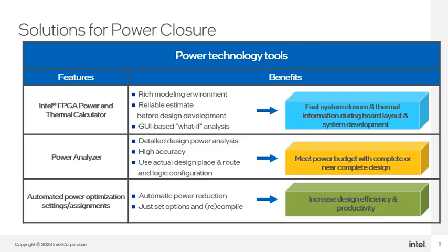The PTC is an easy-to-use what-if analysis environment that can be used as a standalone tool or while using the Intel Quartus Prime software. With the information reported by the PTC, you can choose and start designing the system power supplies and cooling solution, meeting the need of fast system closure.